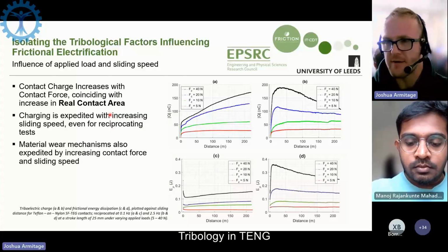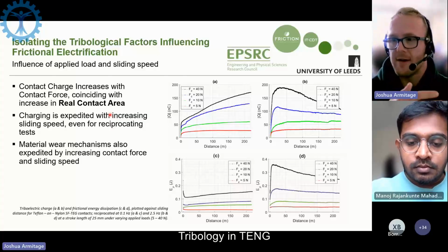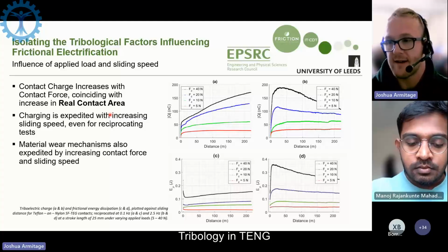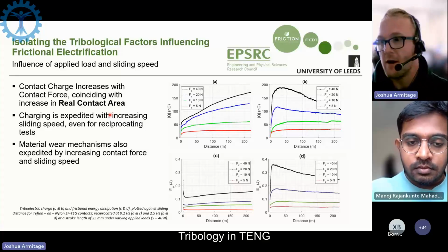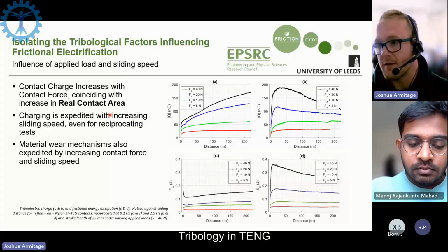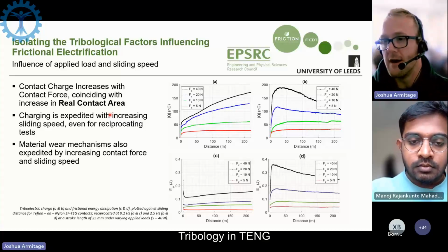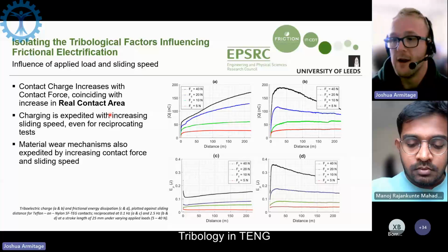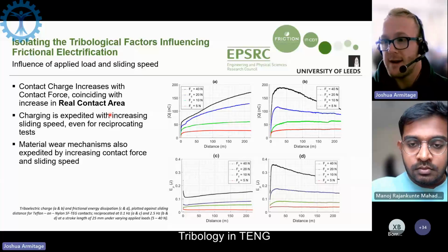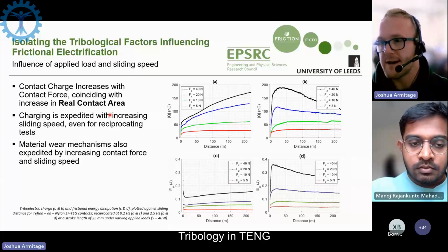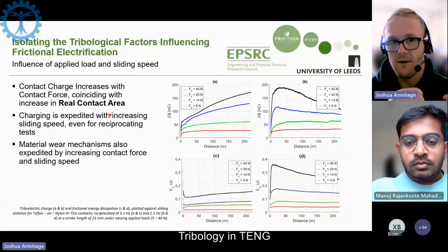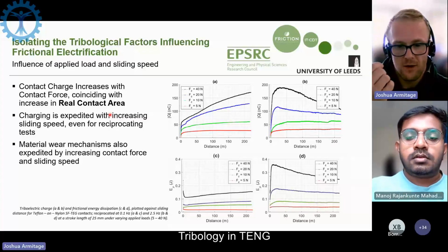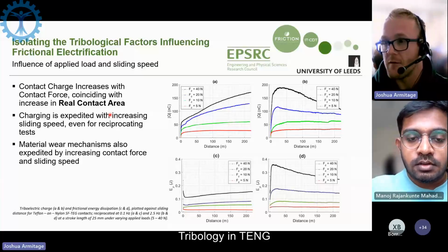So the hypothesis is that it's something to do with the nature of the contact itself that's actually expediting the charge transfer. And right now we're attributing that to the production of phonons, so quantized vibrations, which we're all aware of as frictional heating. We're all aware of acoustic vibrations within sliding contacts, and that's essentially one of the phenomena that is shown by phonons.